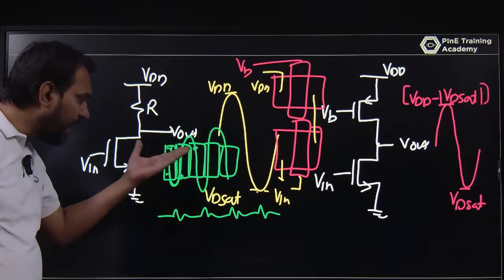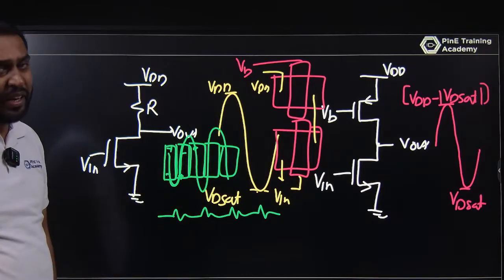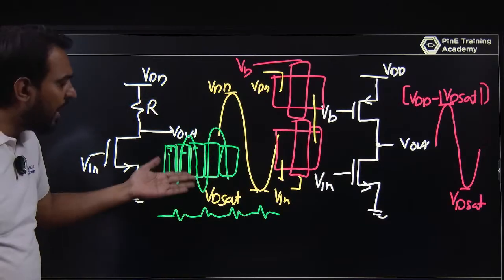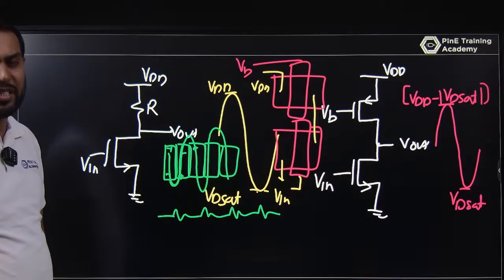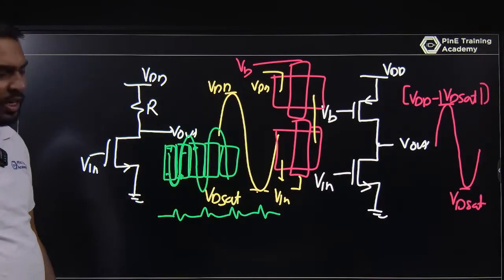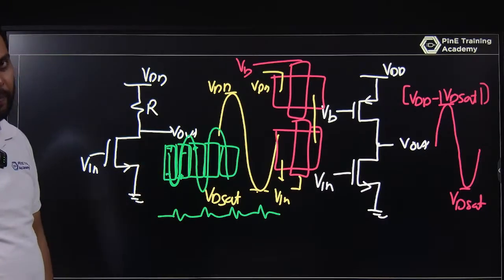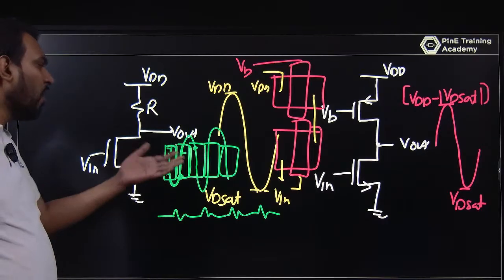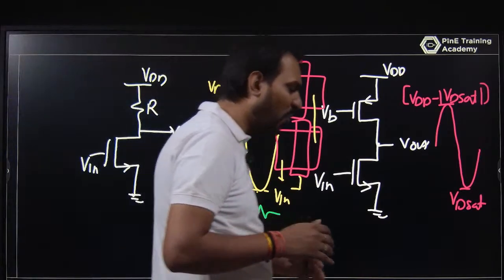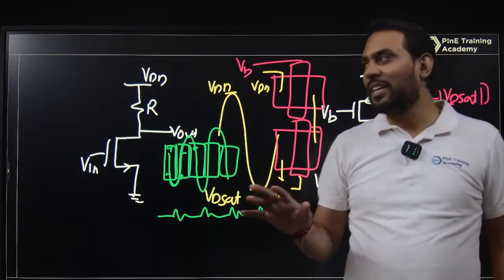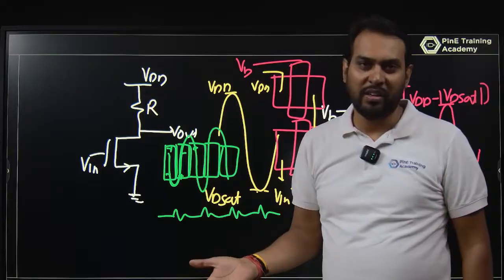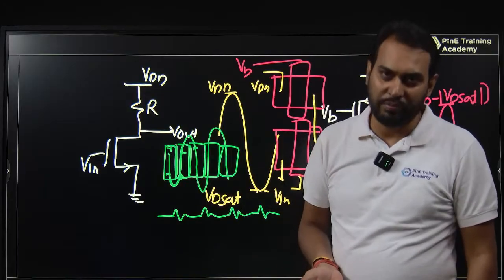And when you go for RC extraction of that, you will find that it is not 10 kilo, it is more than that. That poly also has resistance, and a capacitance also. There are parasitics in there. So an analog circuit designer can use a resistor, but a layout designer will always think, okay, just replace this resistance and use a MOSFET. That will be easy for analog layout.